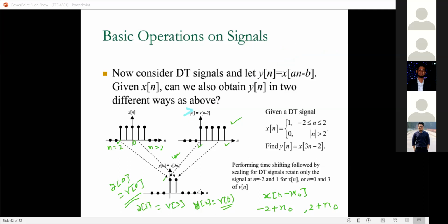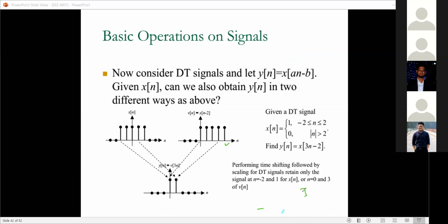The same applies: if you want to shift, you shift your signal first in the original time frame, then you perform the scaling operation on the shifted version. If you want to make the operation precedence independent, then you have to scale your shift with the same factor of your time scaling.